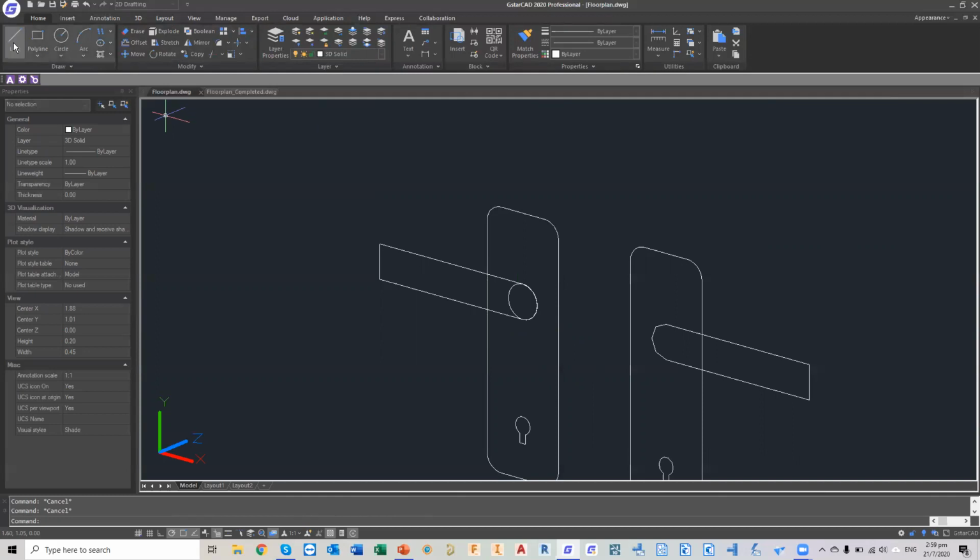Okay, so now I'm going to use the line command to draw out the sweeping direction. So I'm going to sweep from here to the center point of this circle, and then go, oh, this is not correct. Okay, I need to readjust the UCS coordinate system.